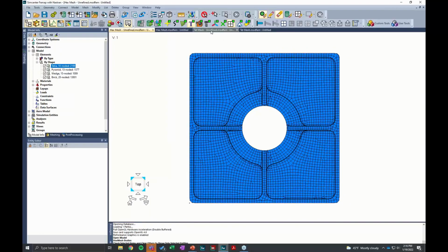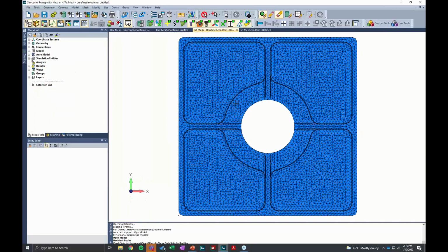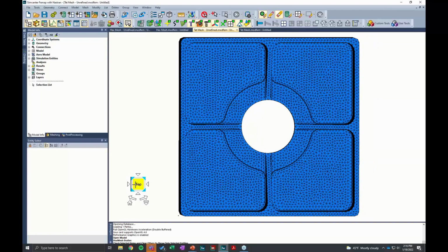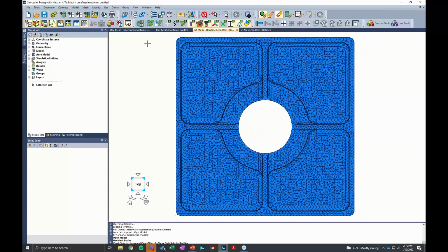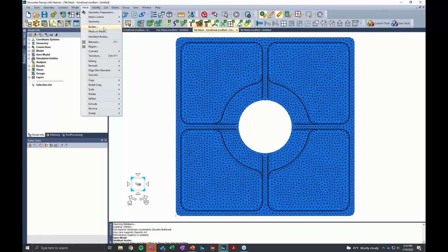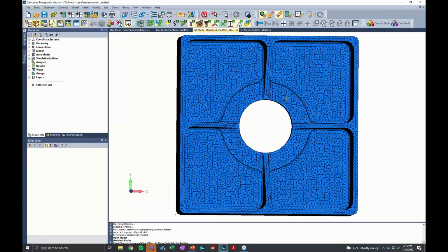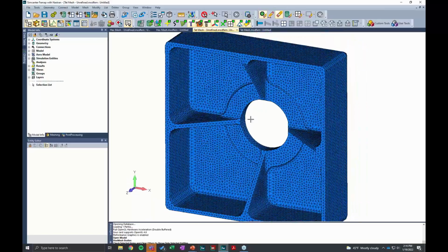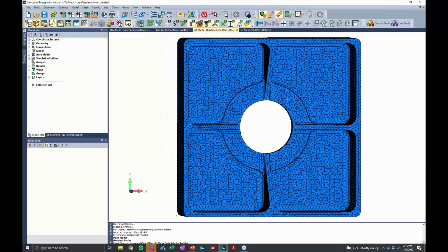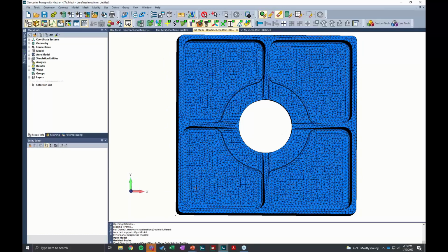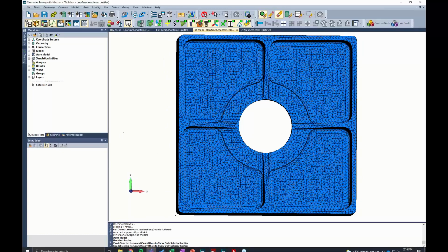I did want to compare to the Tet Mesh version. Here's the Tet Mesh using, I think, a new feature for 2021, the mesh body command. This is without any surface or curvature refinement, and it's basically that I meshed these two bodies with the same amount of resolution.